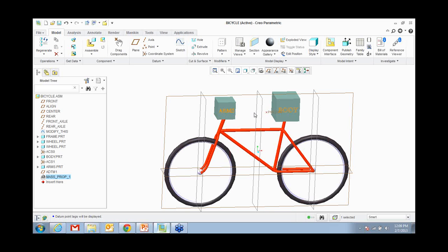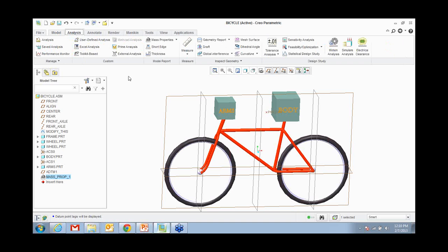Now, center of gravity depends on weight or per se volume, right? So how are you going to determine which dimensions to change so that the CG moves to the required position? Before you make all those changes, we want to see where the CG is, where you want it, and what the distance is that you have to move the CG. Again, CG implies center of gravity. So I measure the distance from the point to the plane. Let's see, the distance is 3.24 inches.